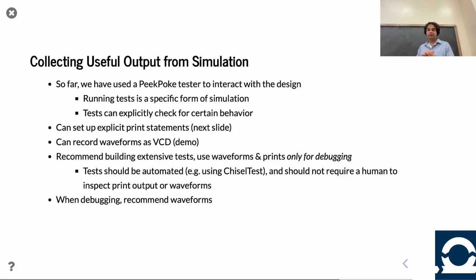A lot of people are printf debuggers. That is possible. One thing that's really nice about hardware, I encourage those of you who have more of a software background to try embracing this quarter, is waveforms. When you do print statements, you the human is saying, I want to print this particular value, maybe put constraints on it. I want to print this particular value under these constraints. Put an if statement around it. With a waveform, you get all values for the entire simulation.